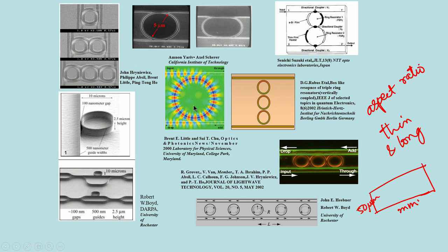One of the important features of the ring resonator is the resonant frequency. As I will show in the next slide, it can operate only at a particular optical frequency. So, this is a frequency dependent device that provides a lot of applications and uses. The variation of this is called the racetrack resonator, where you have a long length for coupling between the ring and the waveguide. There is another important feature that you observe: there is a straight waveguide and a curved waveguide, or the circular waveguide, coupled to the ring. It is not unlike the straight waveguide coupling that we have noted earlier.